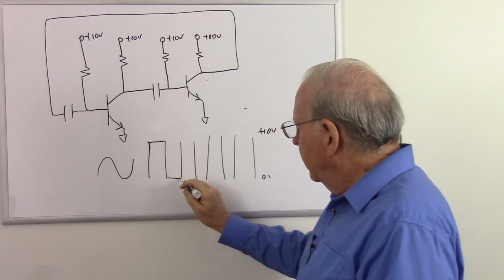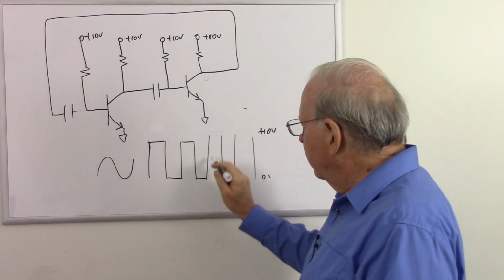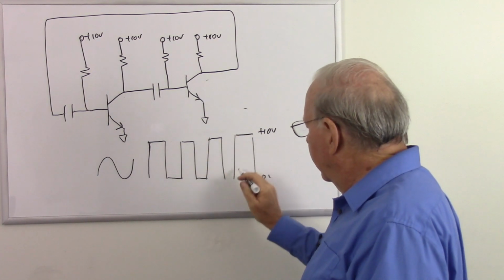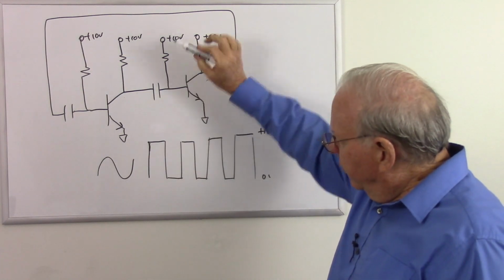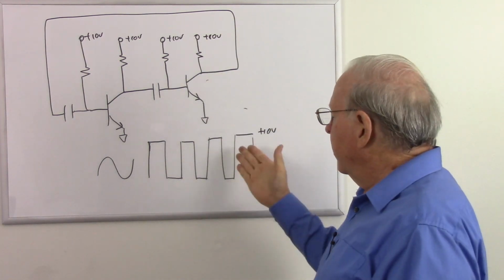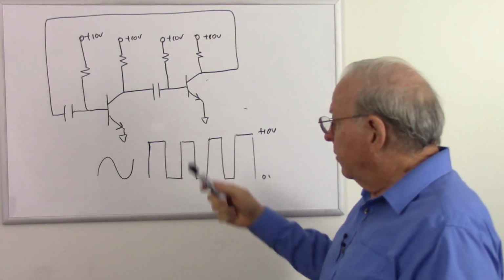So draw the connections. And so swing up, down, up, down, up, down. It just has too much gain. And so we are not going to get a sine wave out of it, but instead we will get this